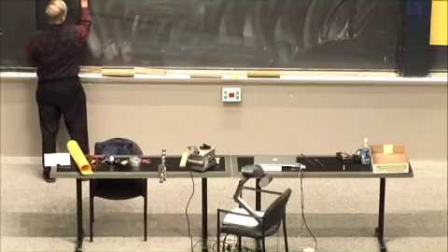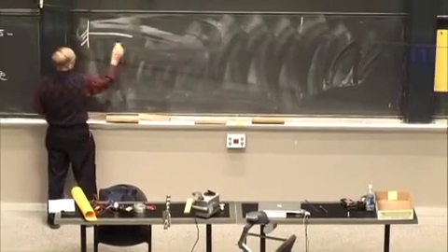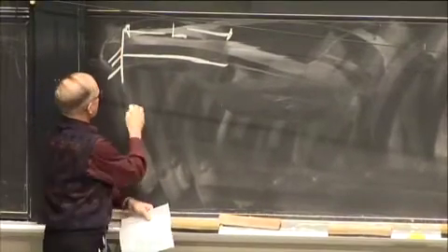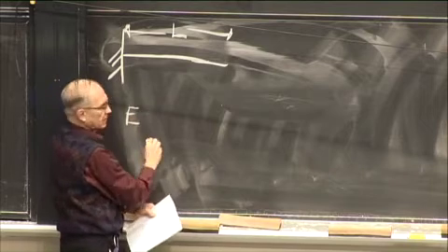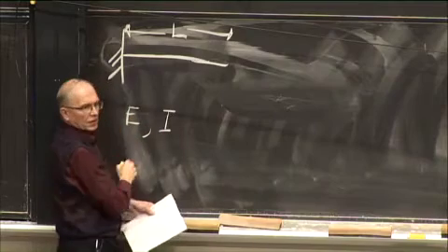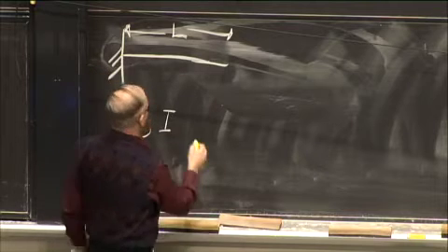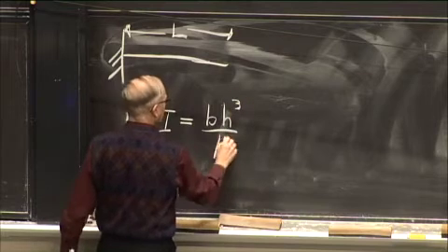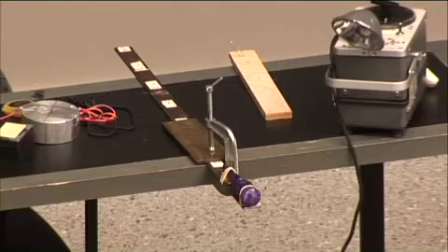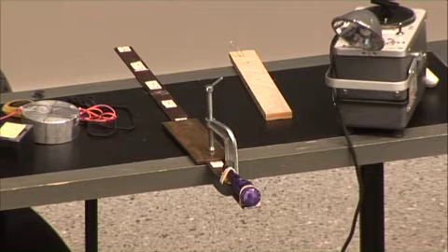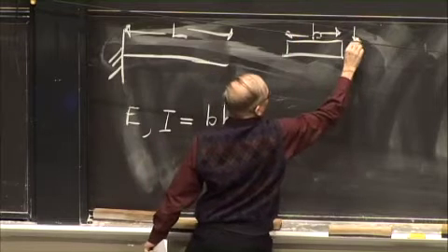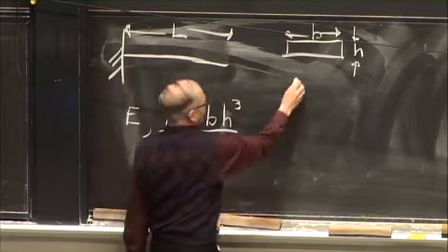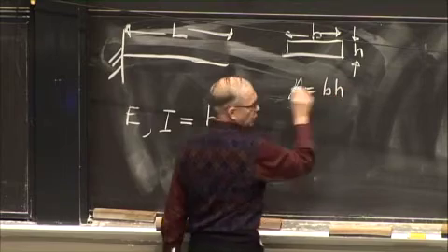So if you have a cantilever, so it's built in at this end, has length L, has some Young's modulus, E, has a property we know is its area moment of inertia, which is BH cubed over 12. It's just a property of the section. This thing has a rectangular cross-section. This is B, and this is H. So it's just a property of the cross-section, and it has cross-sectional area then equal to BH.